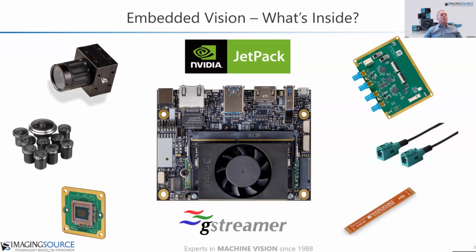This could be board level. This could be also with housing, also maybe with IP67 protected housing. Of course, you need some lenses. You need cables like FPC cables for MIPI cameras or coaxial cables for GMSL2 cameras. In some cases, maybe you need also deserializer boards to connect the GMSL2 camera or FPD-Link camera. And of course, you need a board support package, so the operating system and drivers for the cameras. In case of NVIDIA, it's always JetPack. In case of NXP, probably it's a Yocto-based board support package or anything else.